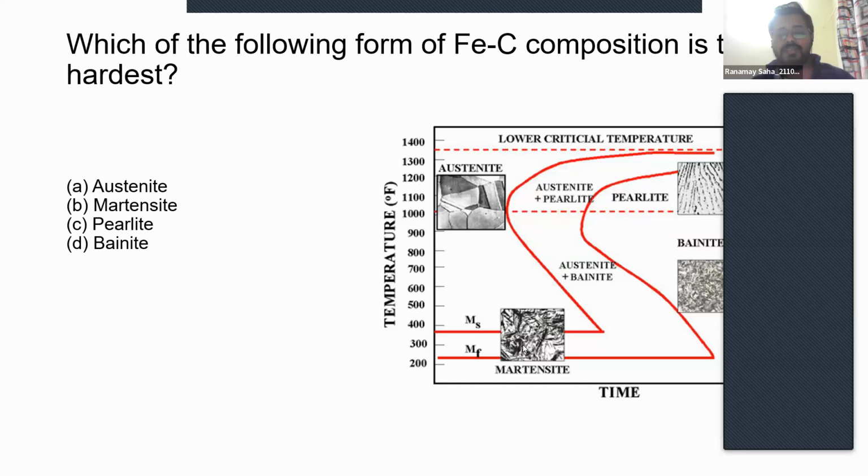So when we obtain martensite, we cannot use it further, so we need to temper it. There is a process called tempering, in which we again expose martensite to a slightly higher temperature than the martensitic structure, where we can get bainite or pearlite as per the application requirement.